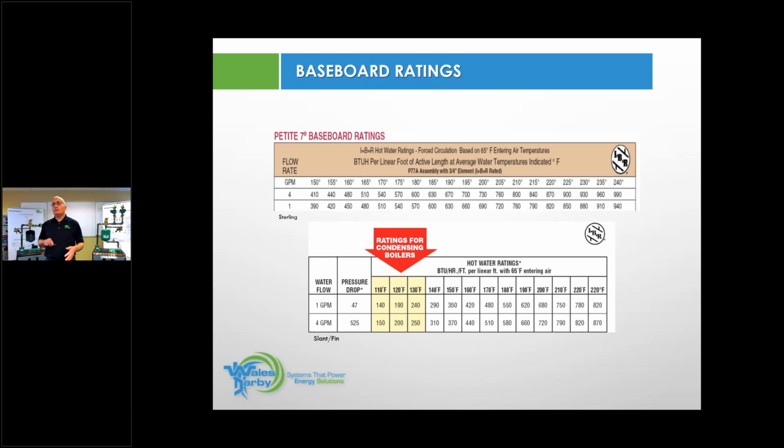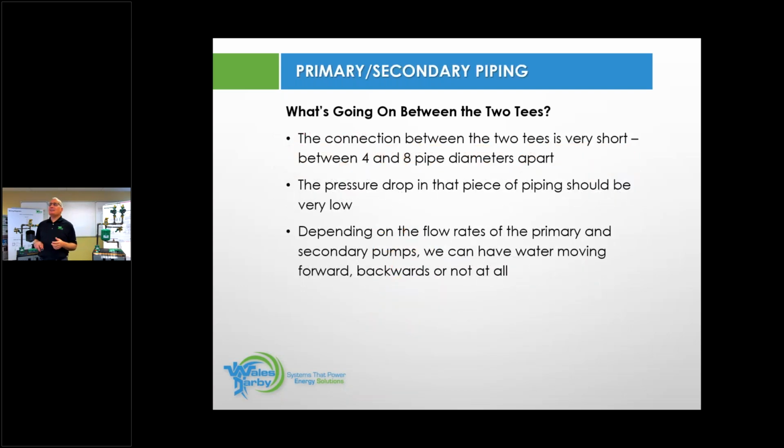So we want to use this, especially when we're replacing a standard boiler, and I want to take advantage of maybe if it's over radiated, I can run a lower temperature, still get enough BTUs out based on my heat loss, and then maybe offer that homeowner a condensing system. Okay, so you can look these up. Every manufacturer has them. One of the best tools you have out there is called Google. You can find anything.